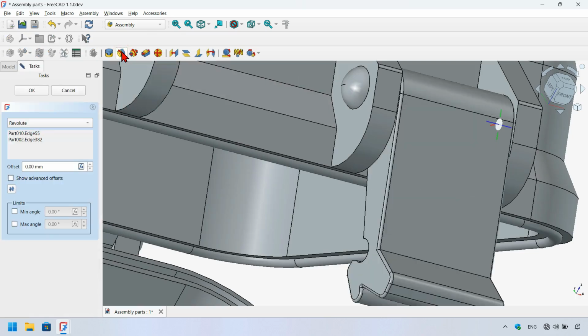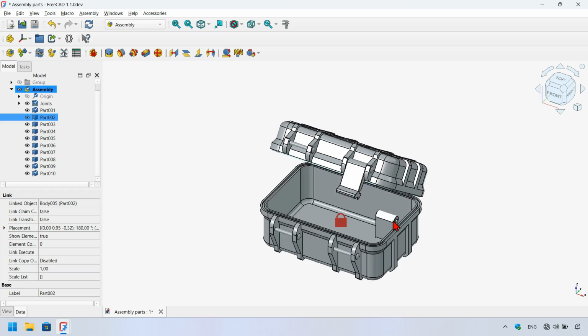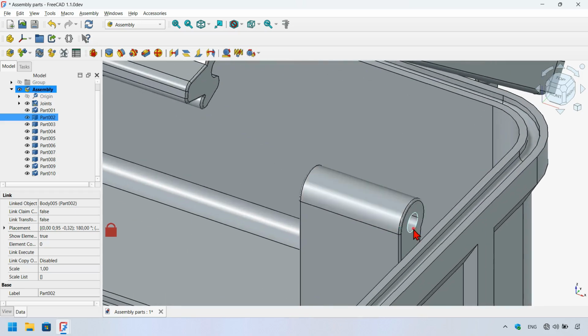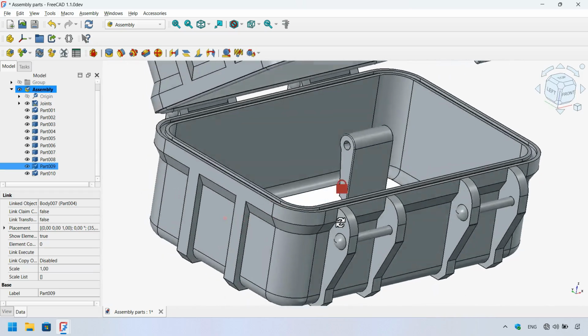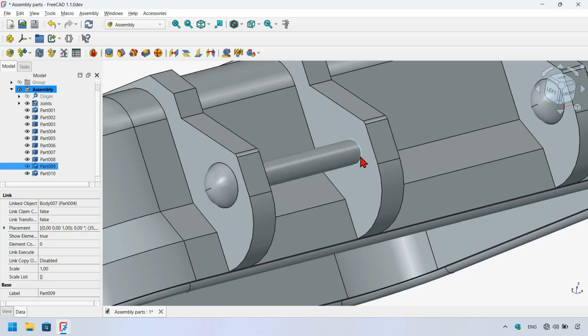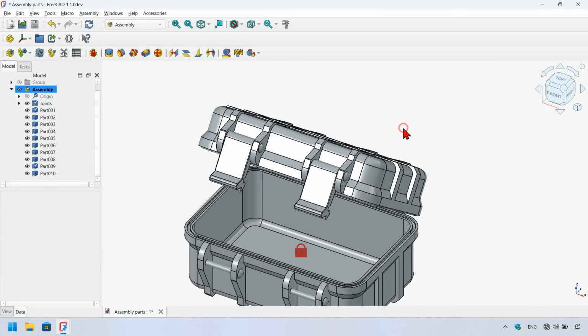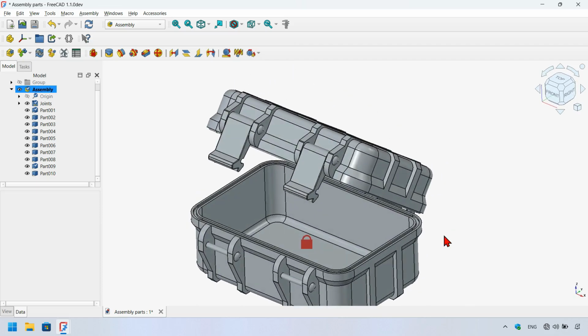joint. I press this icon, I press OK here to finish this, and next here I select this edge, and now I rotate the view again and I zoom in here and Ctrl-select this edge, and now I place a revolute joint again, and now I press OK here, and that's all. Okay, I can press Alt and click on this part here and simulate a motion.